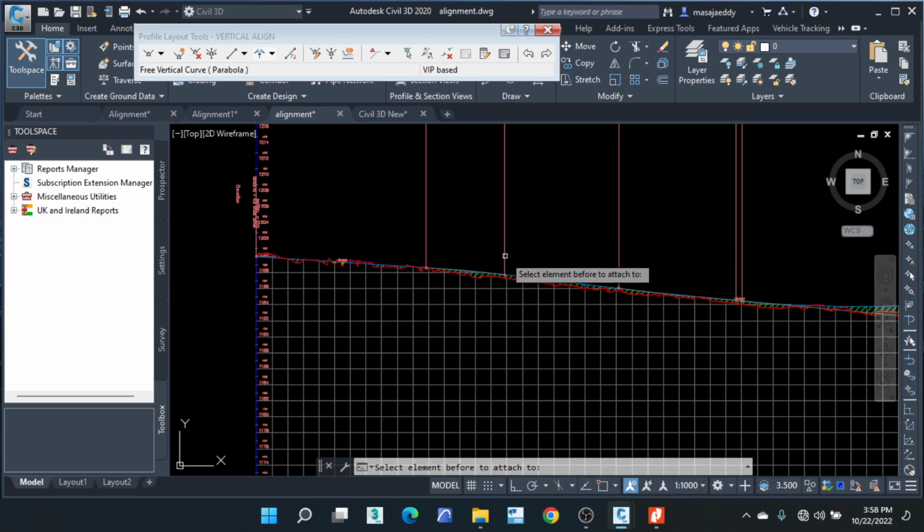Basically for sight distances, if it is below the minimum K value, that means you also have issues with sight distances on the sags and the crests. So that's why you make sure you're above the minimum K value. If it is below and there is nothing much you can do, that's where you have what we call a design departure.